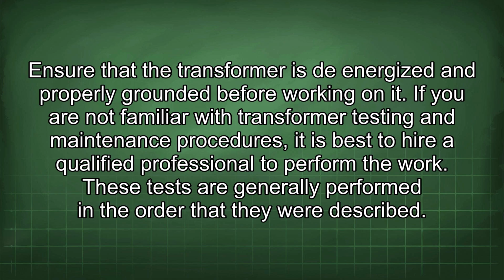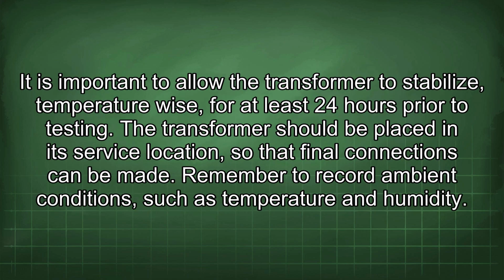If you are not familiar with transformer testing and maintenance procedures, it is best to hire a qualified professional to perform the work. These tests are generally performed in the order that they were described. It is important to allow the transformer to stabilize temperature-wise for at least 24 hours prior to testing. The transformer should be placed in its service location so that final connections can be made. Remember to record ambient conditions such as temperature and humidity.